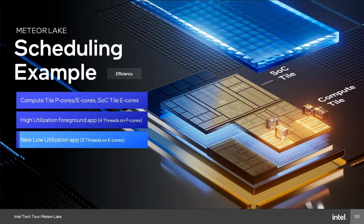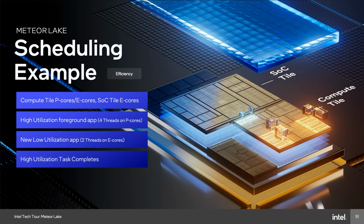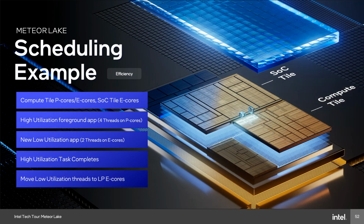But once my foreground high usage, if I'm running a game or content creation, is finished, and I only have that low usage activity, then Thread Director reflects back to the OS saying that, hey, the efficiency ordering has changed. The SoC tile is more efficient, so the work can move there and we can power down the compute tile. So all of this gets communicated to the OS from hardware in terms of this Thread Director table that we provide.